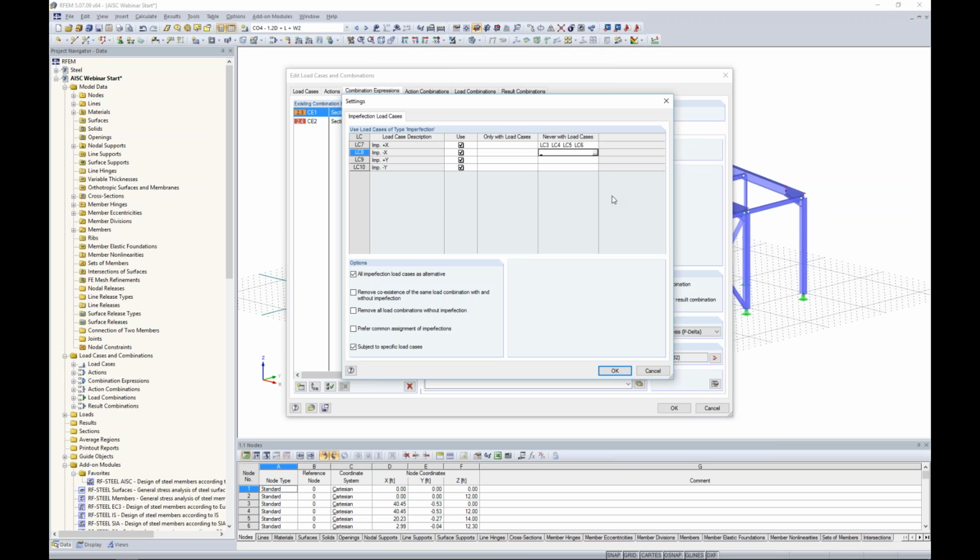with any load combinations that contain those wind loads. If I press the down key, just like what we would do in Excel, and a quick trick, if I hit the F8 key, it will actually copy the entries from the cell above. So I don't need to necessarily go in and redefine these in that additional dialog box.